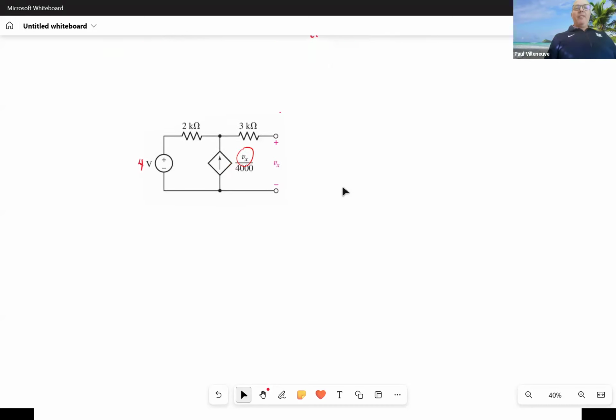All right, so let's solve for V Thevenin first. Let's do the same thing we did before, which is just nodal analysis. We'll call it V1, and we know that V1 is going to be equal to Vx under the Thevenin equivalent case.